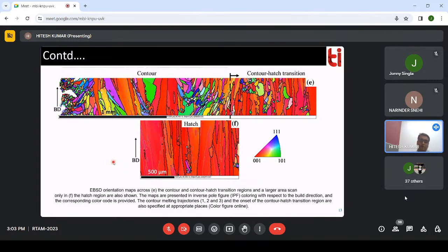Let's talk about it in a more common way. For a material like iron, whenever we use sheet metal formation, in the iron case especially, we try to capture the gamma fiber of your material. Gamma fiber is basically the 111 orientation of grains, meaning in layman's terms, more blue grains in your material.